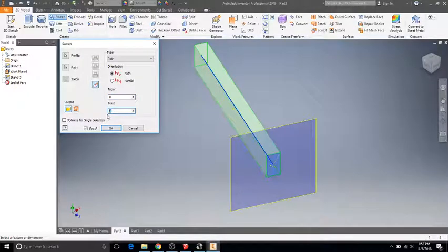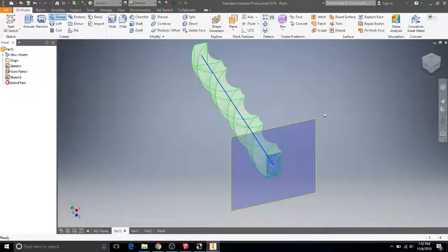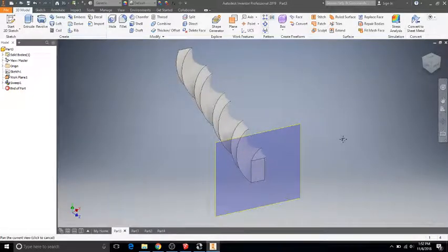You can also add things like rotation. So you can say, I want it to twist 180 degrees. So that whole rectangle is going to rotate 180 degrees as you create your solid. Or how about even more interesting, 720, which is 2 full rotations. Okay, and it creates really strange shapes that are harder to make with other tools. Okay, let's move on to another one.